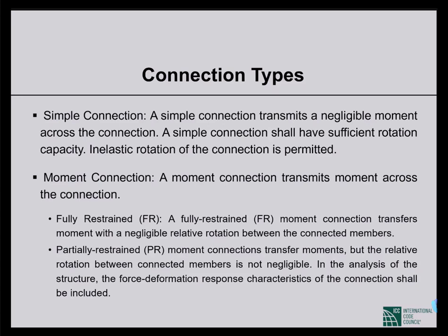So simple connection, though the term is simple, the calculation may seem simple, but there is a big important thing that we shouldn't overlook: in simple connections, the connections do not transfer moment from one member to another, that is from beam to column or column to beam. It transfers only the shear force.